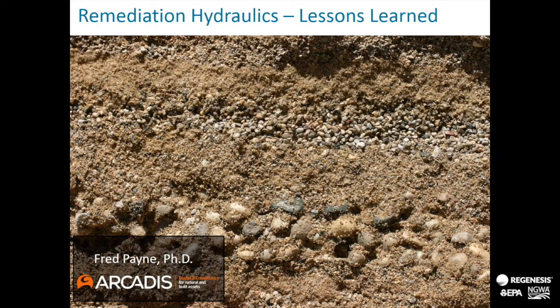So how do we detect this? We need to realize that variation like this, more subtle variation in sorting in sandy aquifers, can generate concentrations of flow that affect where our contaminants are transporting, where our injected reagents need to go, perhaps. We're not really there yet in applying the tools that we have to be able to detect situations like this that are not always as obvious, but they're embedded in almost all of our aquifers.